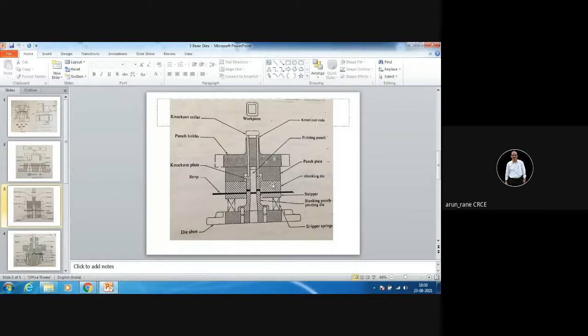Okay, so you have to properly decide upon the sequence whenever you are designing the die or before designing the die. So these are the different components. Now here the workpiece is like this. So obviously you have a blank and punching, blanking and punching. ये ऐसा आपका रेक्टेंगुलर पीस रहेगा ब्लैंकिंग का और ये अंदर ये hollow है so punching रहेगा. Okay. Now this is your die. Blanking die is this, these are your punches.